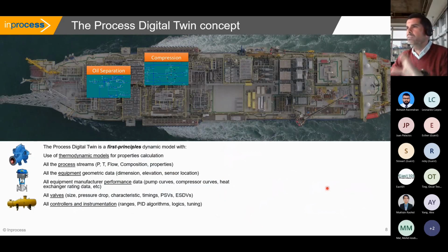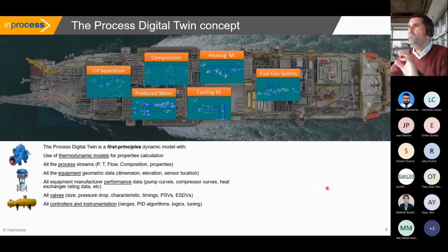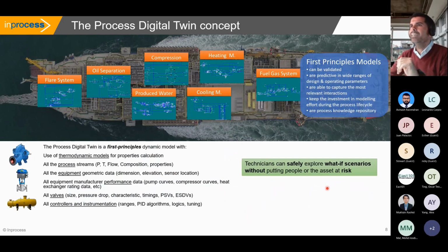Think that when we start talking about high fidelity models, we talk about specific detailed models by using HYSYS, Unisim, etc., to create in detail models of the different packages of the complete facility that include all the details regarding thermodynamic, process, all the equipment geometry data, performance, valves, control, instrumentation data, etc. It's critical for us to explain that when we are building a solution, we start talking about process design and control validation with the engineering team by using this approach, but we move these same high fidelity models and this high fidelity usability to later on be used by operations in their operator training system.